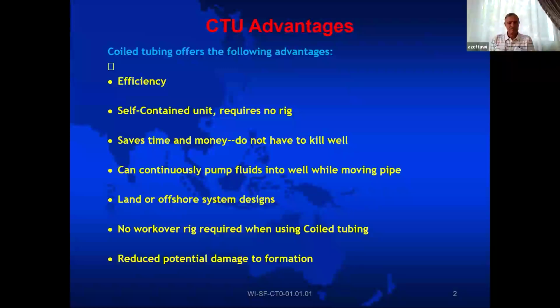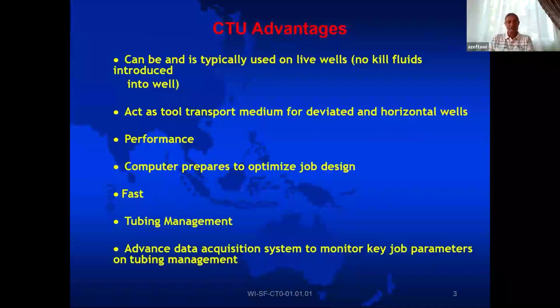We do perforation. We do drilling. We have a coiled tubing drilling rig. We drill the well from scratch all the way to the final stage. So with coiled tubing, just imagine. And yes, we can do it. We do pipelines with coiled tubing. We have sizes now ranging up to 6.5 inch in diameter. But these big sizes, 3.5 and above, we use as completion, as monobore completion, and we use them also in pipelines, especially underwater pipelines.